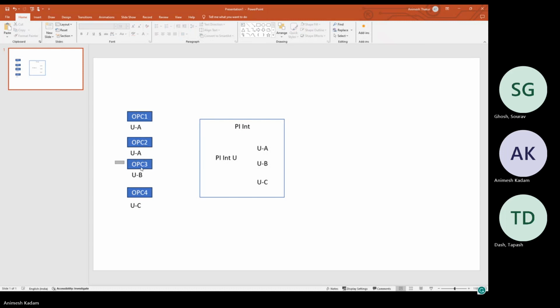And because these users are already created, they will have some extra privileges. So what we suggest is create one user here, and if possible, create the same user on all these OPCs with restricted access, like read-only access to the OPC server. This is the way we do it most of the time. Sometimes the OEM doesn't allow us to create a new user, so we need to create the same user on the interface node. That is the only difference.